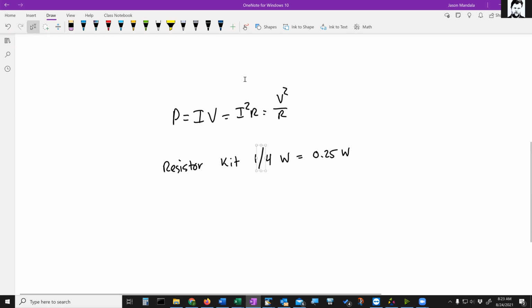So look at this equation. It's multiplied by R, right? So if I took R as 10 ohms versus R as 5 ohms, you'd say, okay, well, the 10 ohms should have more power, right? It's actually not necessarily true because the resistance itself is also going to change the current. So, assuming that you have a fixed voltage, this equation would be more appropriate to use, because the resistance is actually in the denominator here. It still applies with the other equation. It's just a little trickier because R is also going to change the current.